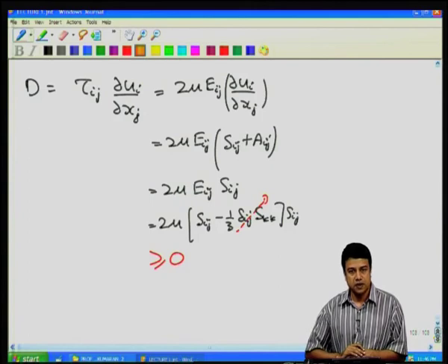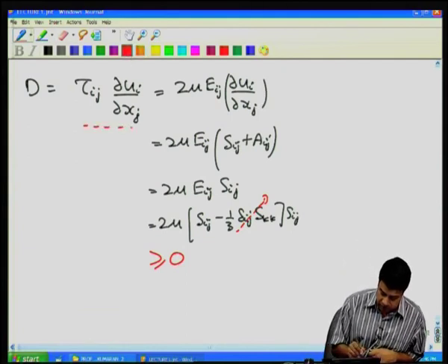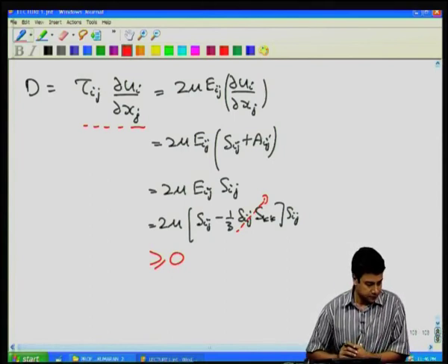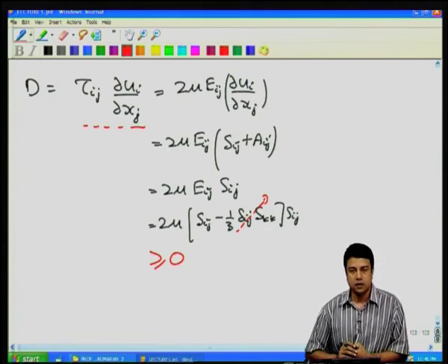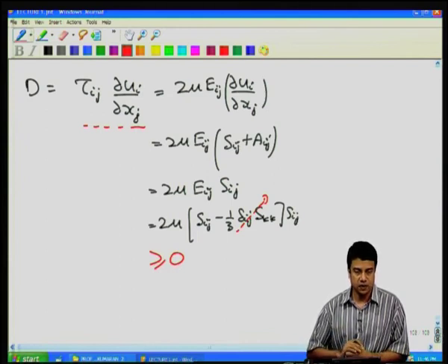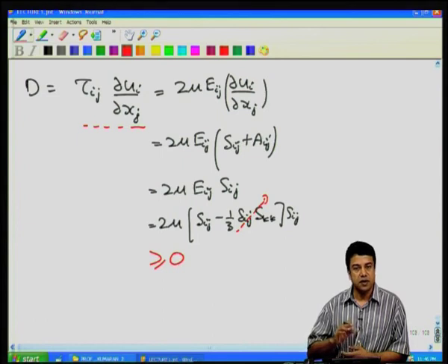Okay. So, that is the energy balance equation. As I said, it is only for the mechanical energy balance equation. Whenever you want to estimate how much heat is generated due to the fluid flow, the dissipation rate in the fluid is basically going to be equal to tau ij times partial ui by partial xj. So, this completes our derivation of the conservation equations, the constitutive relations, the boundary conditions, and I talked briefly about energy dissipation. So, that completes our derivation. Next step is to go ahead and solve those equations.